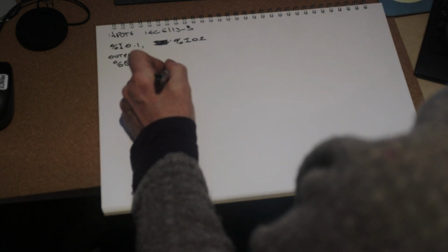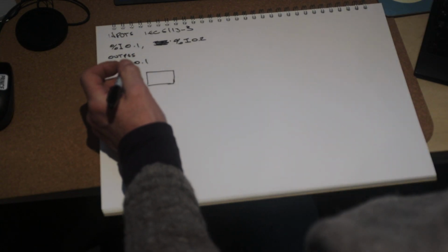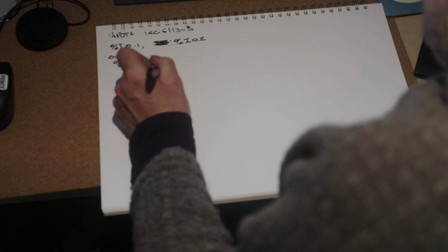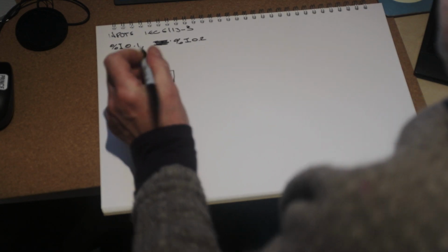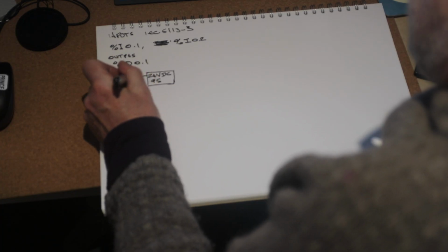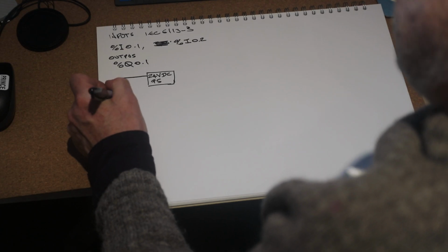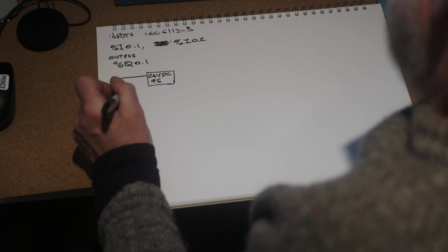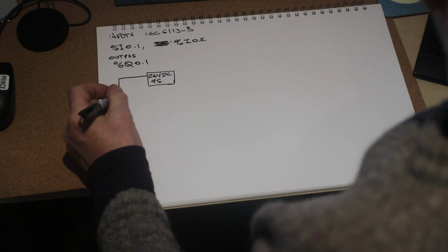First thing you've got is a power supply in the PLC kicking out 24 volt DC, yeah, we know that, we've been using that quite a lot. I'm just going to call it PS for power supply. And then out of there comes 24 volts, very nice. And somewhere along the line we've got an input device, whatever it is, and it could be running potentially at high voltage, but in this case it's 24 volts.